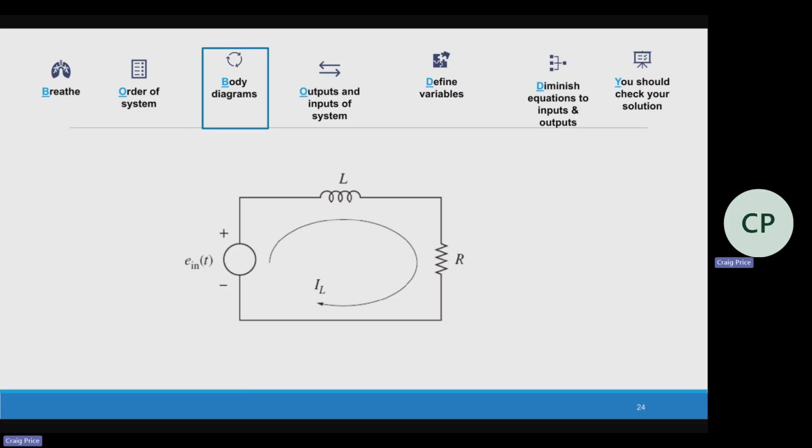It should be positive and then negative for both of them because they are going to be voltage drops. So they're stepping down the voltage. They are not introducing voltage. The only time I have negative to positive is if I have an active element, something that's putting energy into the system.